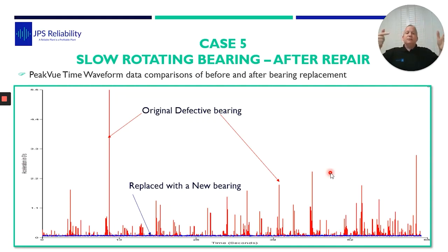And one point of the bearing had the higher damage on the inner and outer race, and that's opposite the greasing point. So it was as if the grease, when it is greased, would come out and couldn't totally replenish around the opposite side. And after 5 years of the stress of the dynamics of it moving and the weight, it just spoiled and failed. And perhaps if they had more grease points around it, they may double their life and actually reach 10 years.